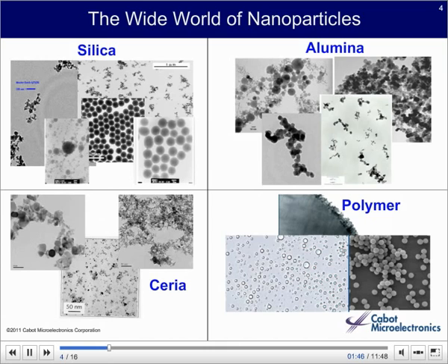Colloidal silica is often spherical, but can clump like microscopic cocoons. The particles can be all one diameter, that is, monodisperse, or a mix, polydisperse. Colloidal silicas are usually made from sodium silicate, or TMOS, tetramethoxysilane. The raw materials our suppliers use have a big influence on the particles they produce.